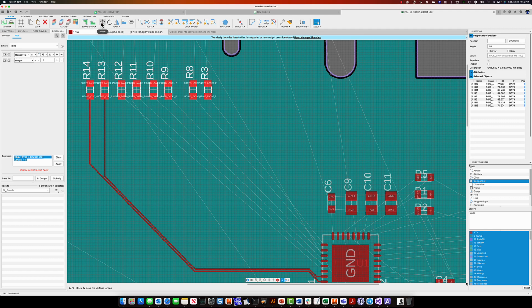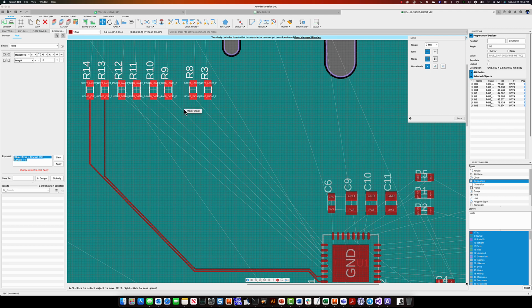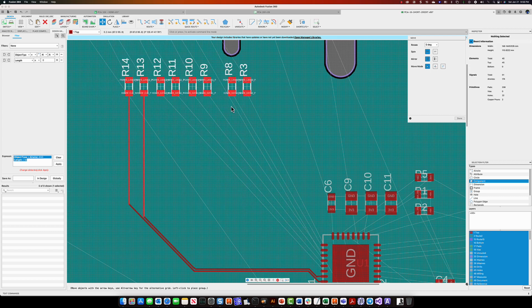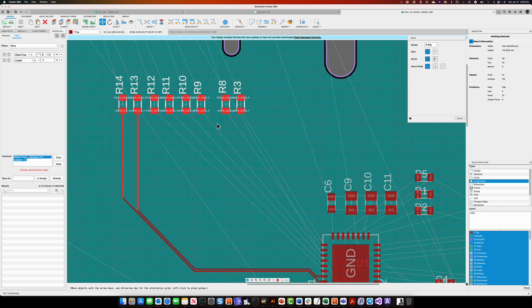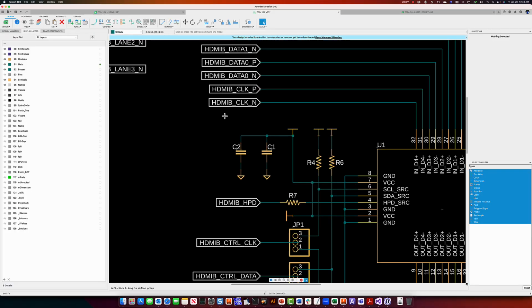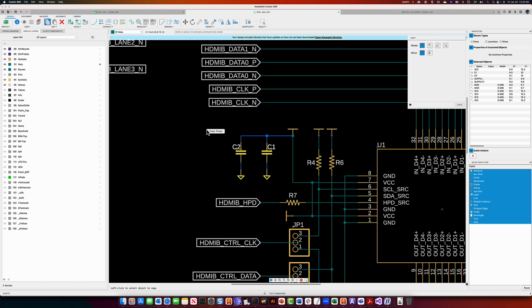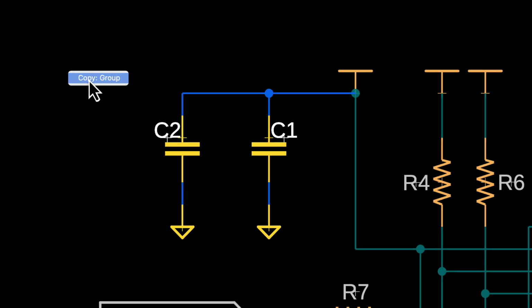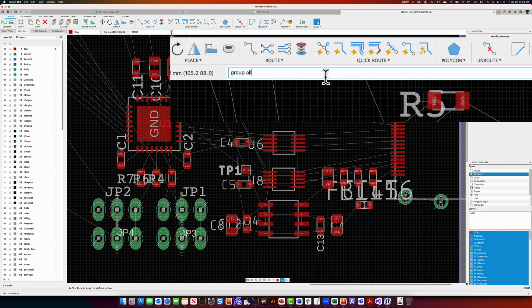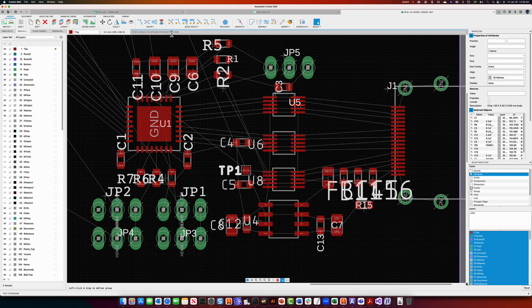When you select things up front and then you apply a command to them, like move or rotate, if you right mouse, you have the option to apply that to all of the selected items. And this is going to become an important feature of what I'm going to describe in the command line. So let's say that we want to do something like change all the fonts in the design to use a true type font.